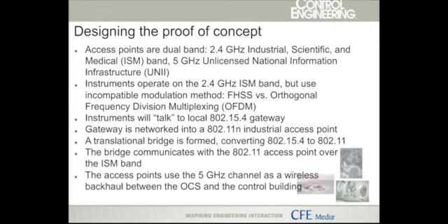The instruments use WirelessHART, which is Highway Addressable Remote Transducer, an old wireline instrument diagnostic and reporting tool, which has been adopted for wireless.